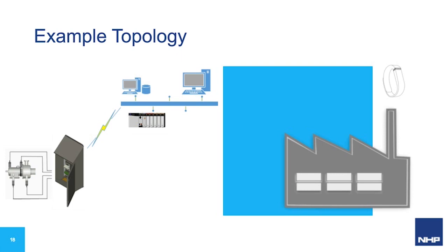The benefit of that is it contains everything that you need to essentially connect to the machine on the left-hand side, but then for connecting it to our existing control system. So when we connect to our existing control system, we're essentially using a compatible RS Logix 5000 or a Logix Designer in Studio 5000 as it's been known for the last few years. And we can simply add it like a remote I/O module. And what happens then is we use an add-on profile within the PLC programming environment. So think of an add-on profile like a configuration template where you can simply put those values in.